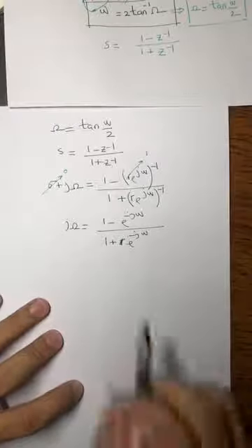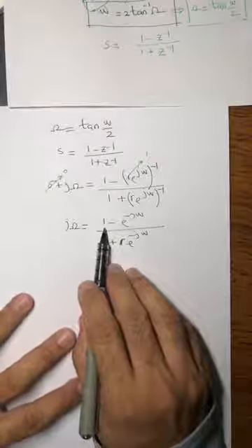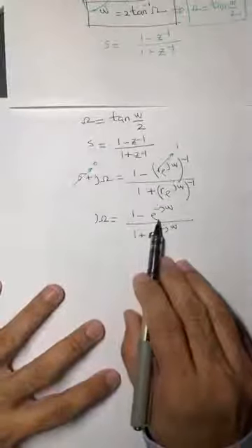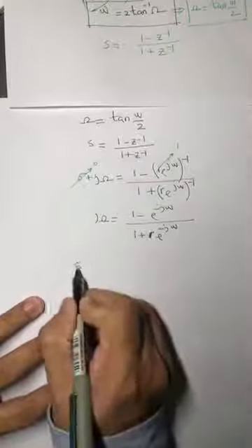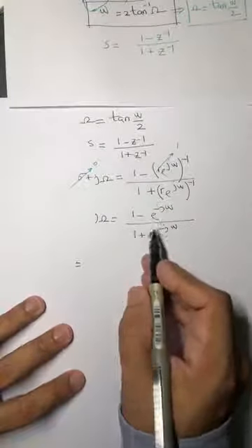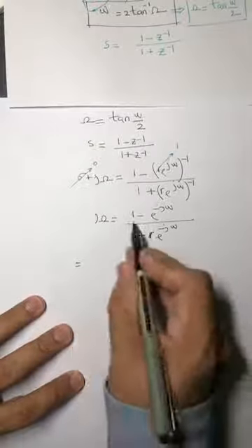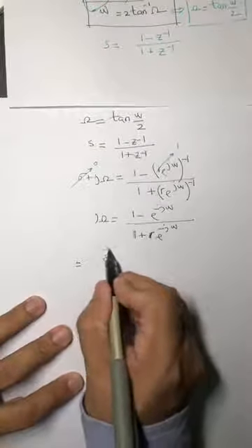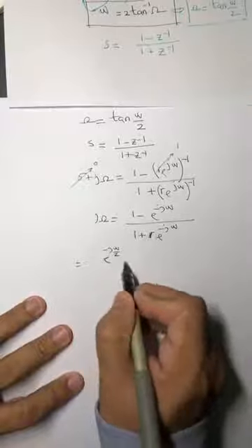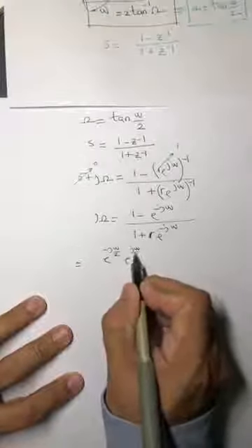Now what I can do is split this one into two. This is a technique which is very common in signal processing: if you have this expression, you can simplify it by splitting into two exponentials, minus j omega over 2 and plus j omega over 2.